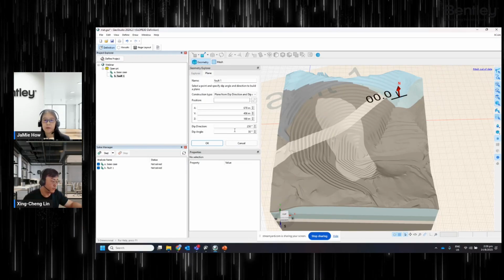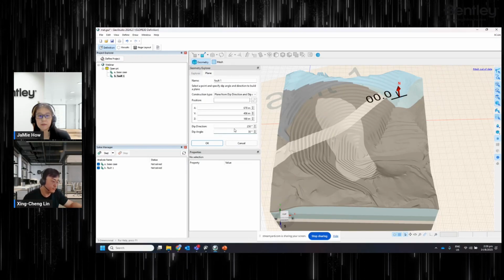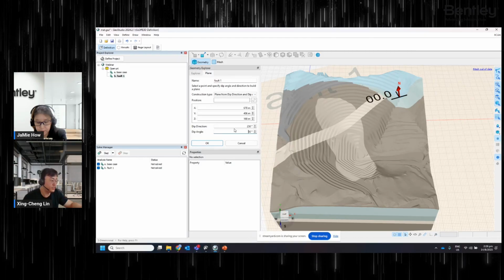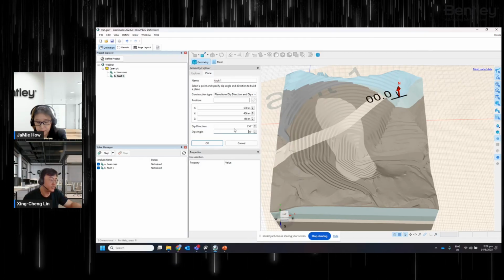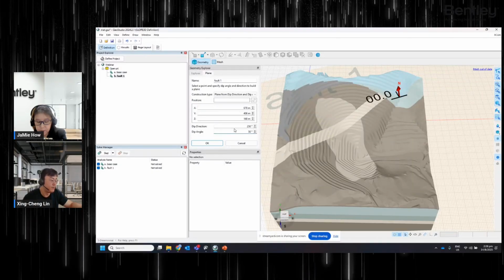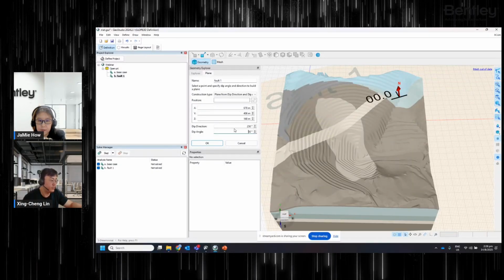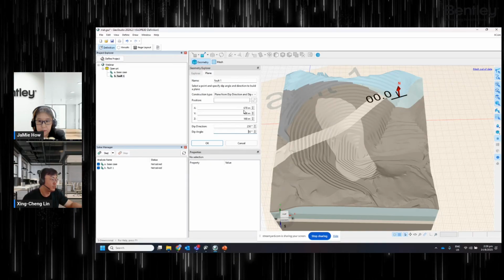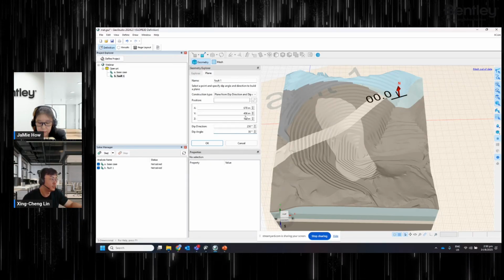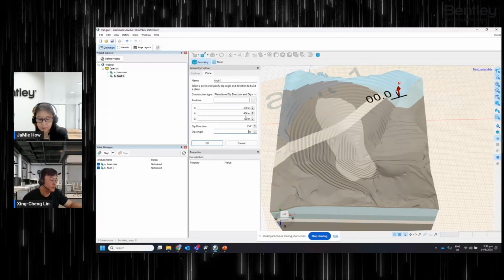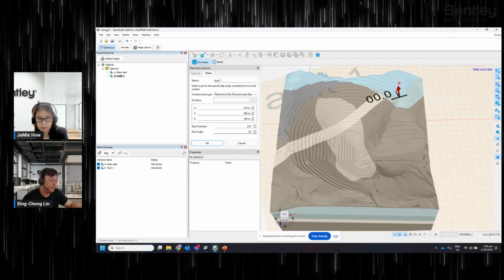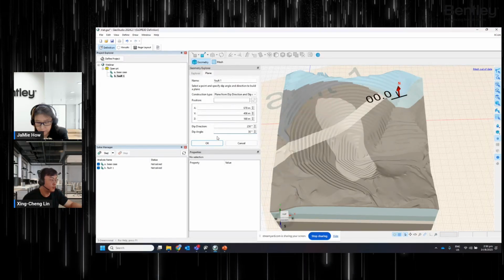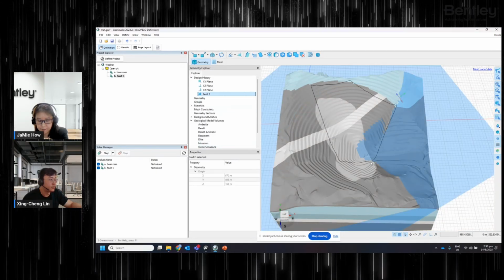So remember when we first brought the geological model into GeoStudio, the first thing we did was to remap the axis. And there's another key piece of data, which is the base point right there. When we first bring it in, the base point is the furthest extent of that model domain. Once we remap the axis and adjust the base point, everything got shifted over and changed its orientation. So we need to take this into account when coming up with the input of the plan position in terms of the XYZ coordinates. All right, once we see the intersection point symbol showing up there, that's about to move up. So click OK. So this is the fault.